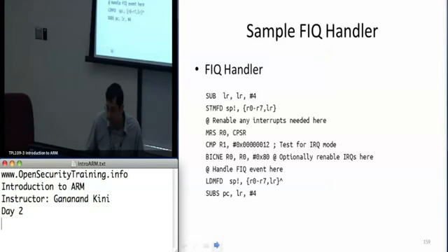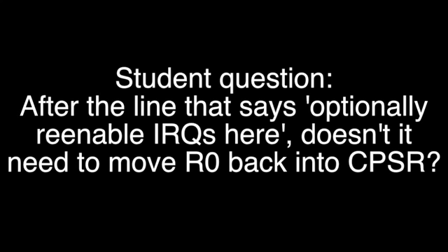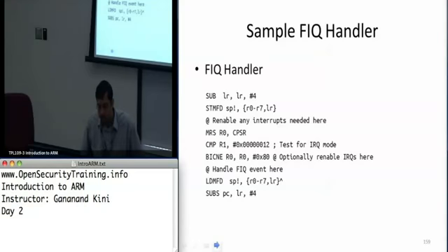Actually, no, because if you remember, so once it's set the CPSR here, once you do the PC LR, you're going back to, yeah, I think this example, I was trying to go back to the regular mode and whatever was set in when it came into the IRQ or the FIQ handler. So it's just going to take the SPSR and whatever mode it was running in, right?